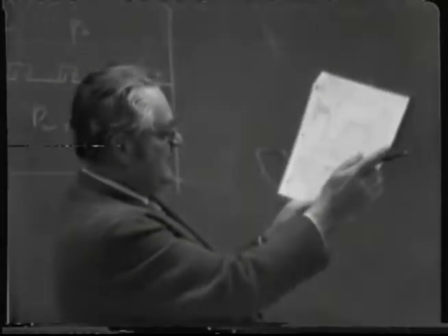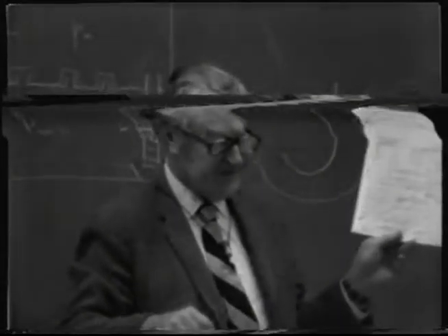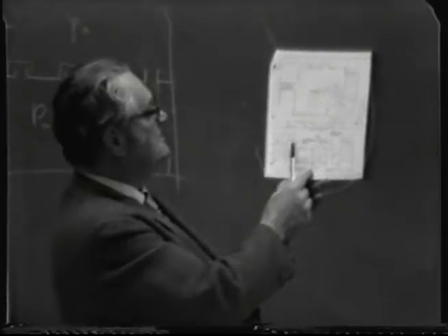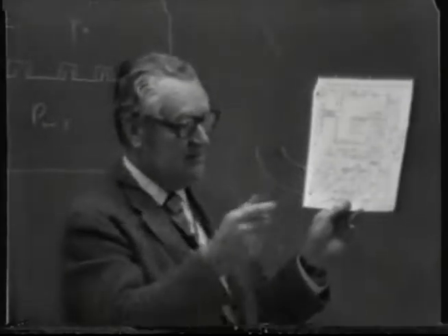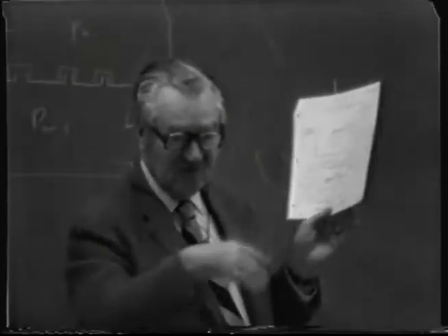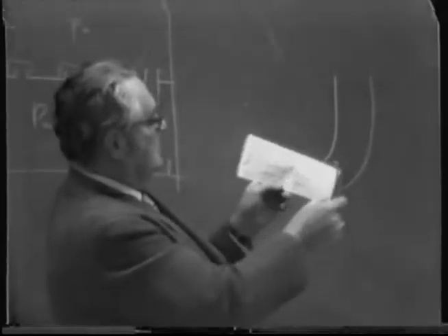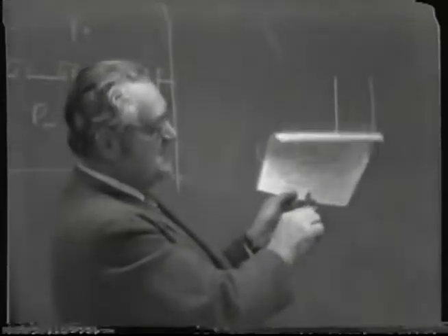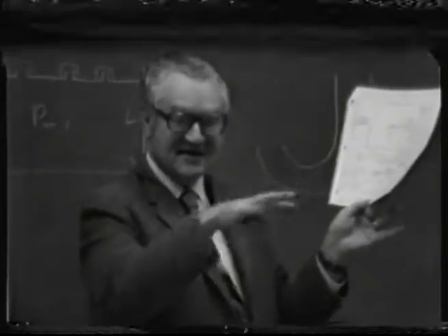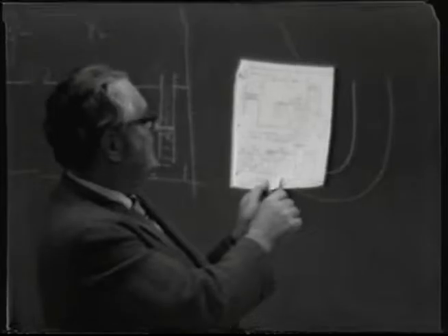But at the same time, up at the top of this is another one of these vapor recompression devices. And so the high pressure steam from the boiler is allowed to expand again, reducing the pressure laterally to the direction of flow, and creates a partial vacuum, which then causes some of this stillage to be flashed into vapor, and it goes up here and then mixes in a kind of a cascade arrangement, a shower type column if you want to think of it that way.